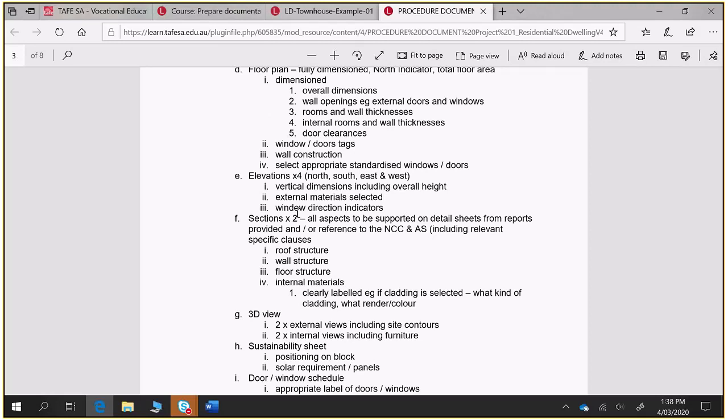As a general rule, with your sections and your model, as soon as you drop a section line in there, you'll see there's not actually all that much in this model. It's pretty bare bones. You'll be doing detail lines from there on, and you might even be scrapping stuff as well. You might decide, I don't want to show this because that slab thing is not right and there's erroneous information there. You might want to hide it in view, and just rely on detail lines.